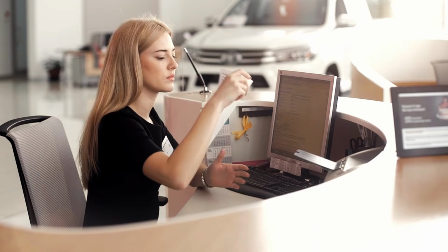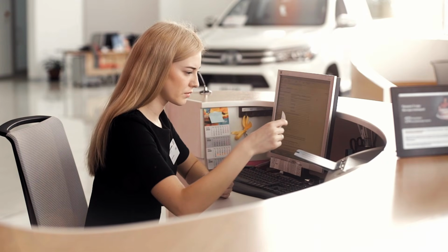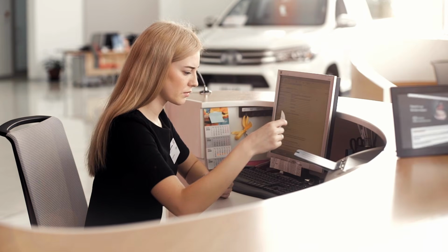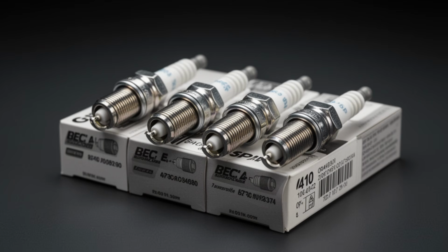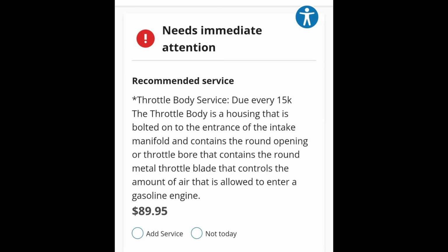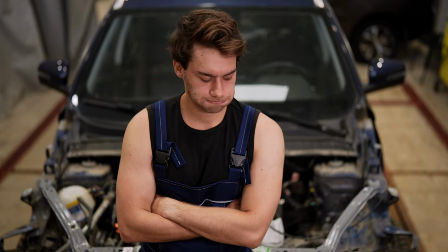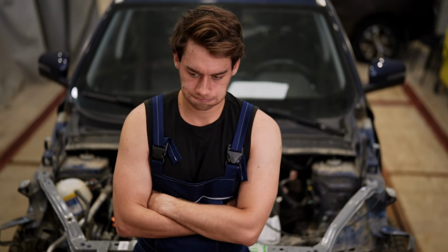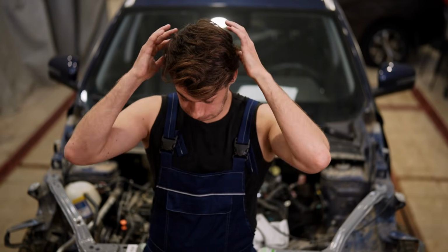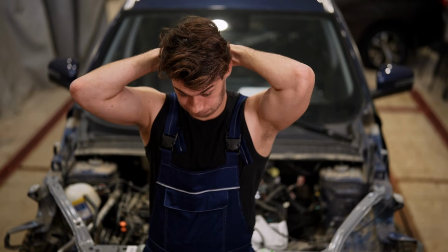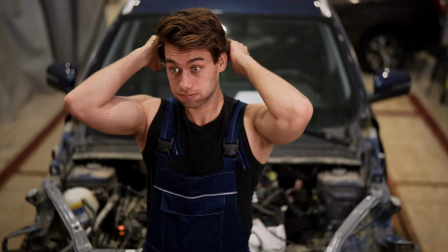The contrast between this $5 cleaning procedure and the service items it replaces is worth stating explicitly. A new set of spark plugs on a 4-cylinder engine, $40 to $80 plus labor. A throttle body cleaning service at a dealer, $60 to $120. A set of new oxygen sensors, $80 to $200 per sensor. None of these address a fouled MAF sensor. If the MAF is the root cause of the fuel economy loss, all of those services will produce partial results at best because the data error feeding the ECU has not been addressed.